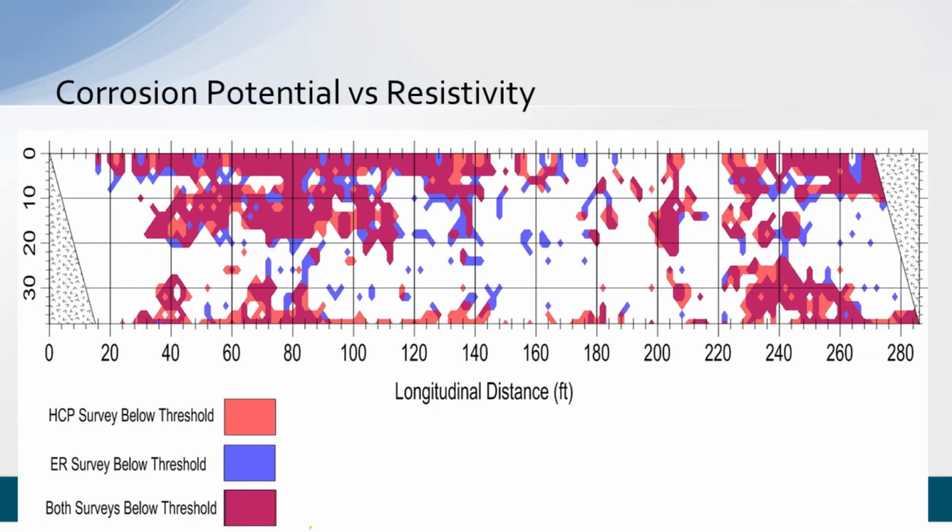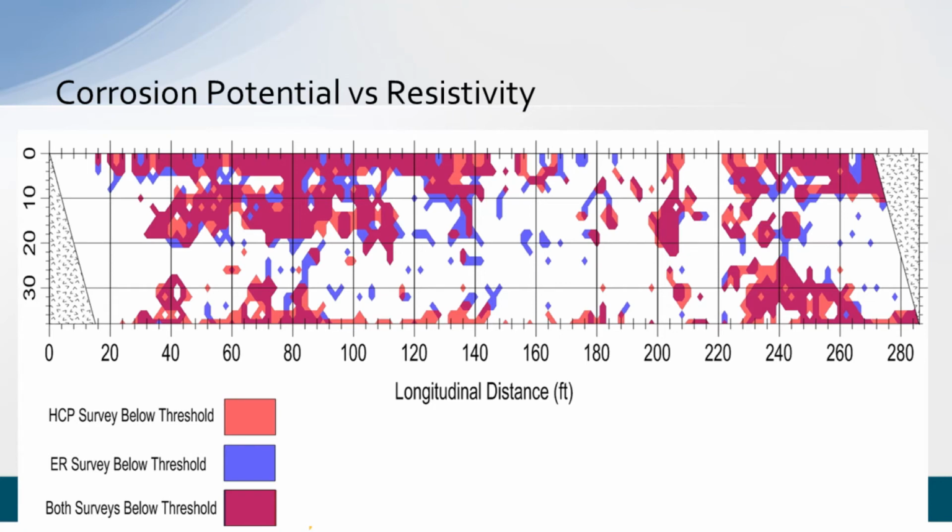And so here we have a resistivity survey of a bridge deck, and you can see typically when you're below 40 kiloohm centimeters, that is an environment conducive to corrosion activity. That number, some people say 30, some people say 50, but it depends. It's not an exact threshold. But you can see there's areas of active potential corrosivity environments here, and the probability of active corrosion when you have a resistivity less than 10 is pretty high.